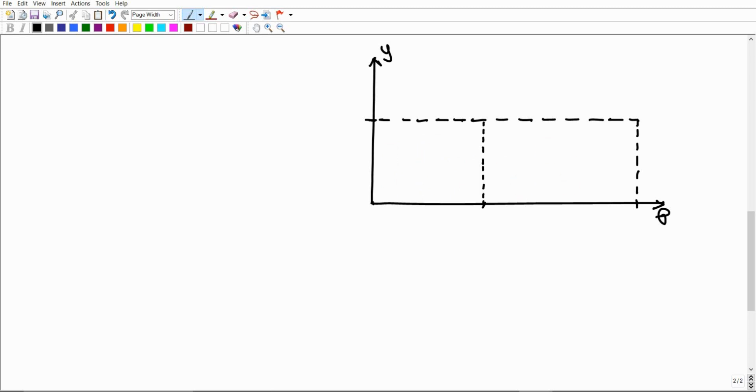Then how about the second period? The second period should be dwell. The dwell is just for 30 degrees, which means just 1 centimeter. So you're just gonna measure 1 centimeter and mark a point. Then from this point, you're gonna draw a vertical line to define the second period as well. So I'm gonna draw this vertical line in this way to define the second period. Make sure that it is perfectly vertical.